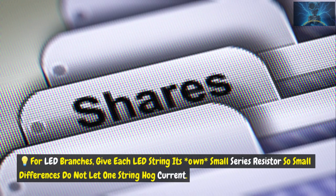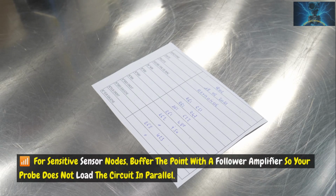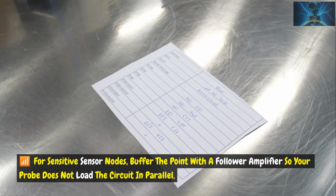For LED branches, give each LED string its own small series resistor so small differences do not let one string hog current. For sensitive sensor nodes, buffer the point with a follower amplifier so your probe does not load the circuit in parallel.